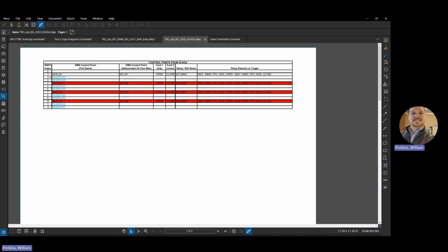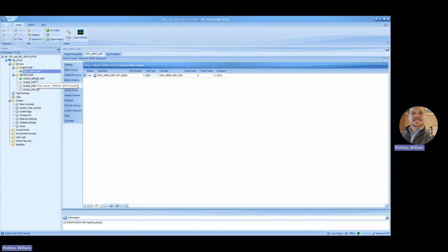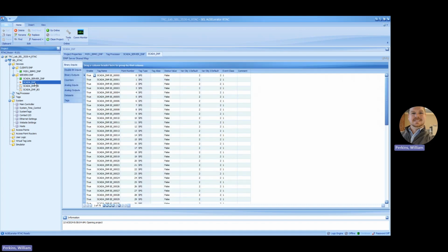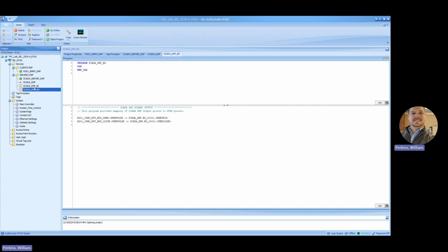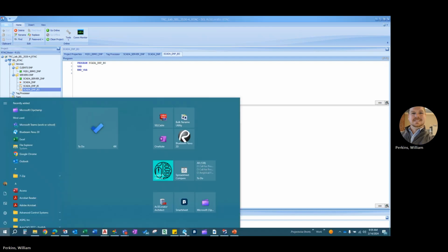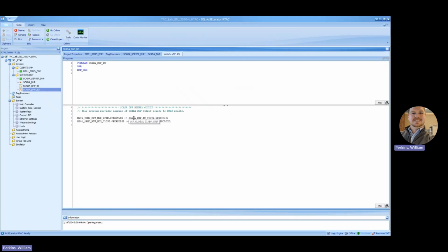And this map is identical to the map that is in the RTAC. If we go to the SCADA server DNP mapping, we can see that in the binary output status, we also have the 0, 1, 2, 3, and so forth. The logic behind those points, in order to map it from SCADA to the motor operated switch, you can see that point 1, which again, DNP index point 1, is directly mapped to the oper pulse.